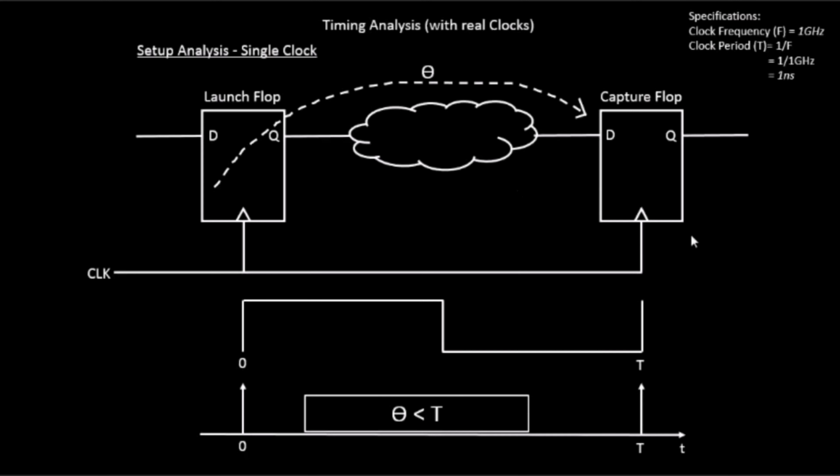So how do we do that? Let's try to first build the clock tree over here. So it will be something like this. The clock which enters from this particular port first hits the first buffer over here, then at this point it diverges. From this point it goes to the launch flop through one buffer, and then goes to the capture flop through two buffers.